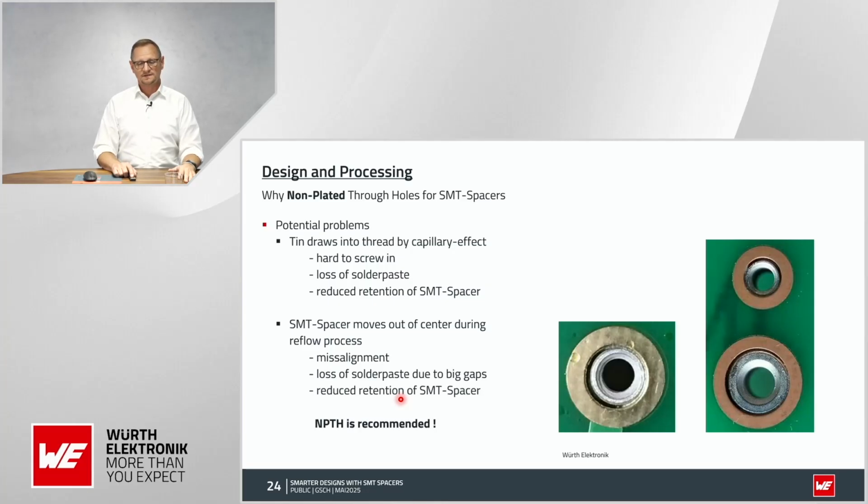So misalignment is a big problem, especially if you have more than just one spacer on your PCB. Imagine you have 4 or even more, and you need to hit all the holes on your top PCB. Maybe through the tolerance it runs out of the tolerance and you can't screw some screws in. And therefore a non-plated hole is originally recommended.